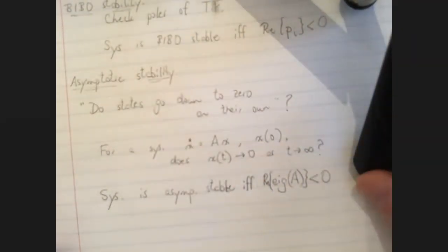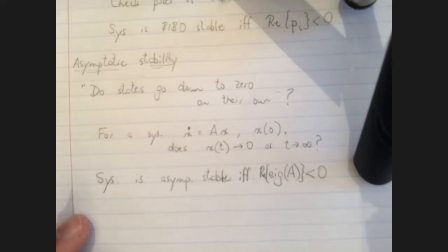So again, pretty similar to what we did with the poles of the transfer function. Here we are checking the matrix A and seeing, okay, what are the eigenvalues of A? Then take the real part of that, and is the real part negative? Again, this corresponds to the left half plane. All right, so that's the other type of stability. We'll be able to see that there's a relationship between these two. This one is all about input output. This one is all about all those internal variables going down on their own.